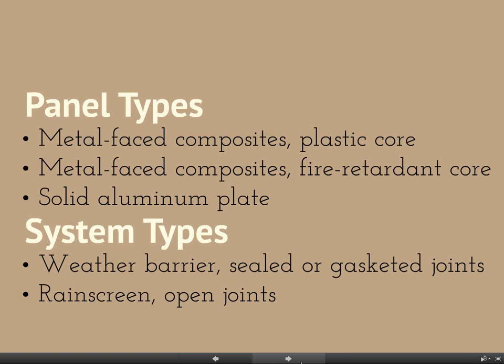Although I think, because the plates are probably sprayed in a plant as opposed to coil coating, if you use the same paint, it should look pretty much the same, but there may be some minor differences. I can tell you that that's not true from experience, because when you lay up the painted product, especially in metallics, as Vivian's saying, if you take a piece of coil sheet, like an edge flashing, and you're field forming it and you cut it and lay it up one way, cut the next piece, turn it upside down, same color, it'll look entirely different.